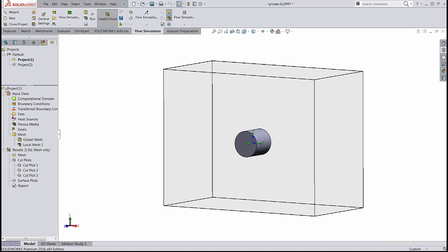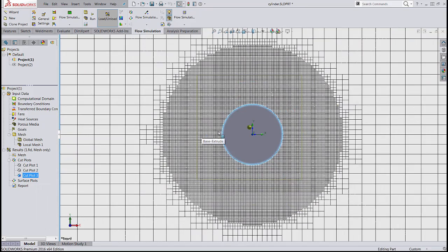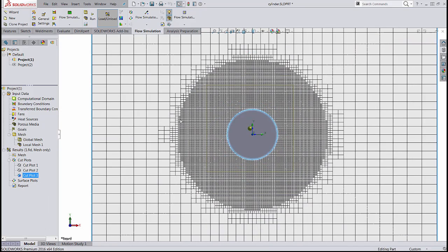If you look at what the mesh looks like after these mesh settings, you can see that the global size, as seen on the outsides, is relatively coarse. We had 0.01 meters radially outward as the first equidistant size away from this face, and then the second step, which is slightly more coarse as compared to the first one but finer than the global size.